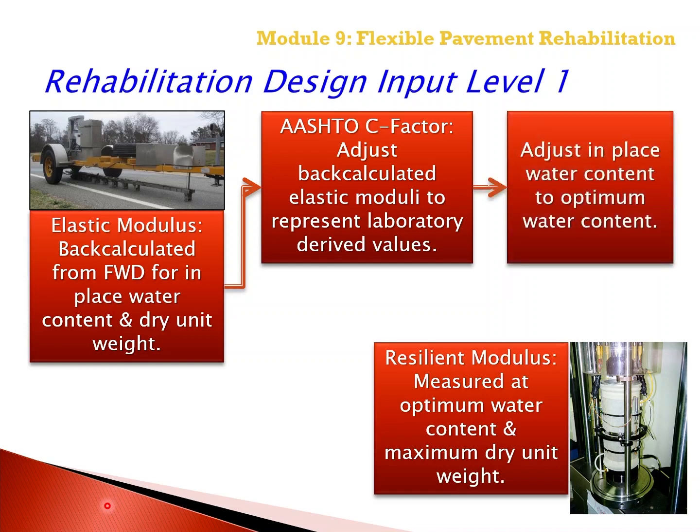So we adjust the in-place water content to optimum water content, and that is used to represent the resilient modulus that has been measured at the optimum water content and maximum dry unit weight in the laboratory for the global default values relating resilient modulus and the volumetric properties under controlled testing conditions.